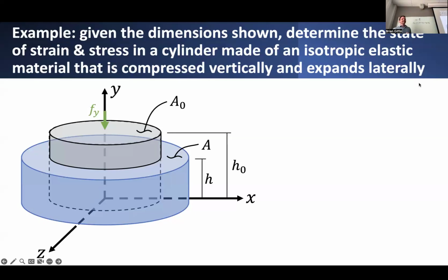We can do a similar thing for areas rather than volumes, in which case the area strain associated with the deformation of this planar surface, let's call it epsilon area, is just the sum of the longitudinal strains in the plane of this planar area deformation. In particular, we'll call it epsilon XX plus epsilon ZZ in this example.